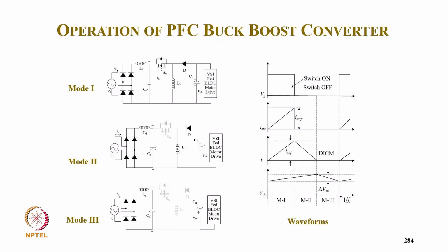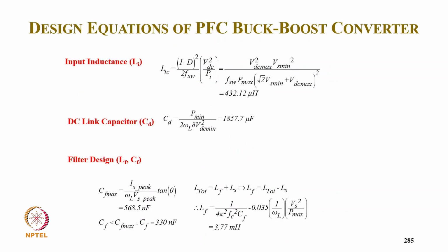These are the different modes of your buck-boost converter. We have switch conduction, diode conduction and the two inductor modes, and the corresponding waveforms, showing how the current and voltage waveforms typically look.